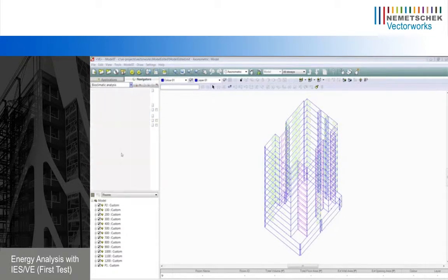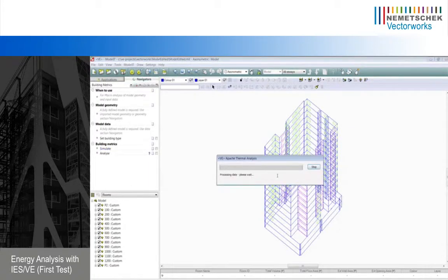Building materials, building metrics, so I can get an idea for the properties of the actual building. This will allow me to analyze things like how many rooms are within 25 feet of an operable window if I want to look at natural ventilation. It'll tell me what my effective depth of daylight is based on window height. And it'll also let me know how many stories my building is, what sort of materials to avoid, etc. So this is going to take just a minute here for this to run.